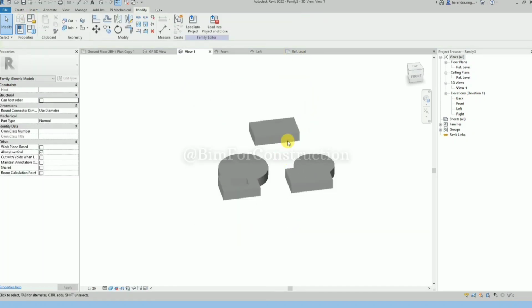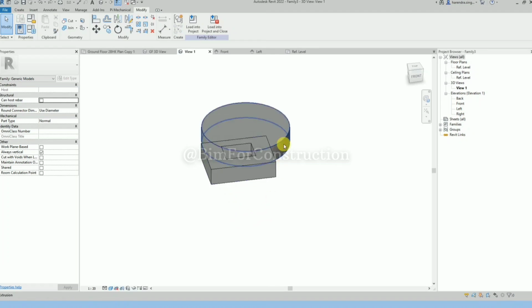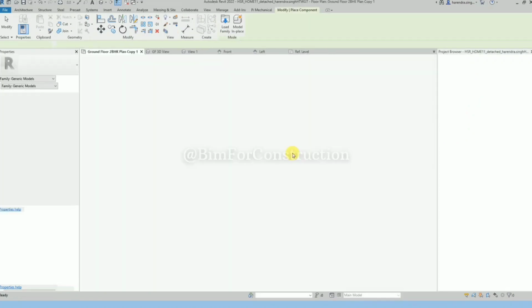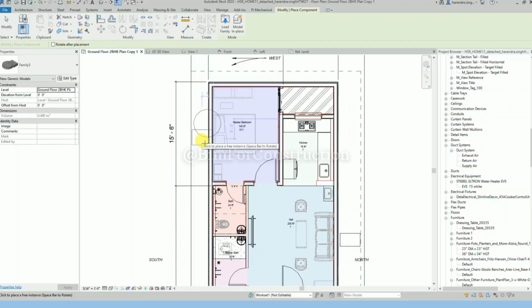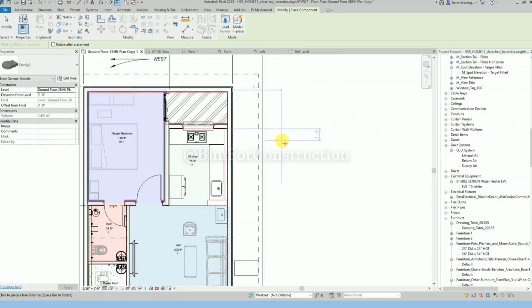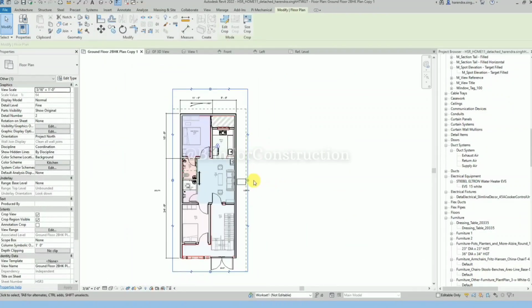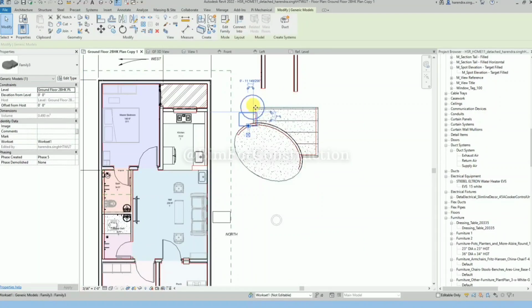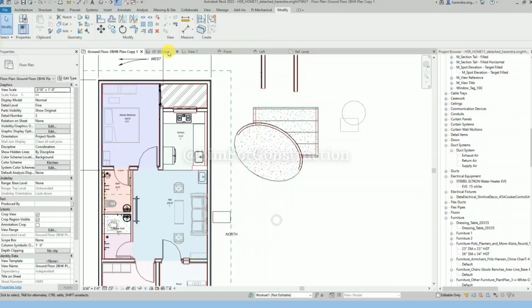Simply go to create, then select the surface like front, top, left, bottom as per your project requirement, on which surface you want to place that connector. In the front face I have put the duct connector, and you can then adjust the duct connector parameters like length and height. And simply I have loaded my family in my current project.